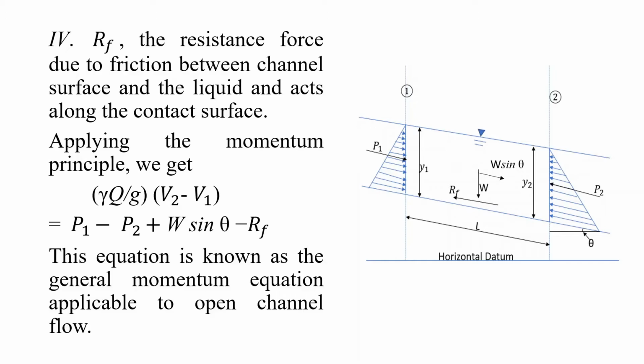Now, applying the momentum principle, we get γQ/g (V2 - V1) equal to P1 - P2 + W sin θ - RF. So this equation is known as the general momentum equation applicable to open channel flow.